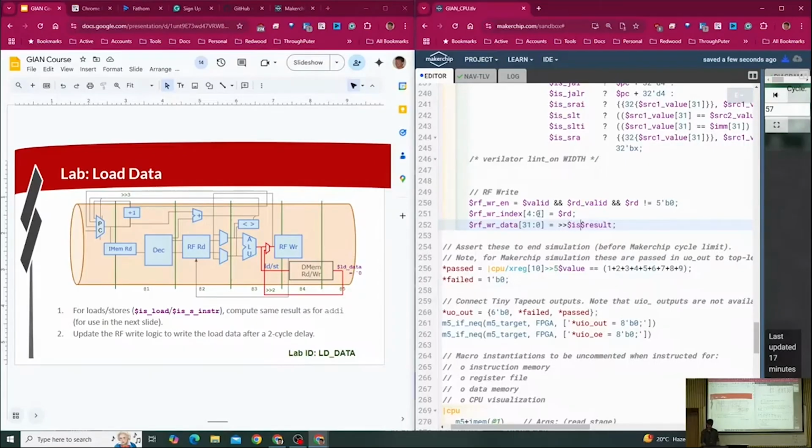So if it is a load, and 2 cycles ago, then we want to write the load data also 2 cycles ahead in the pipeline. Otherwise, we want our default behavior. So in the case of load, we have created the shadow. So the instruction 2 cycles later is not trying to do anything else. We'll use that time to inject the load data.